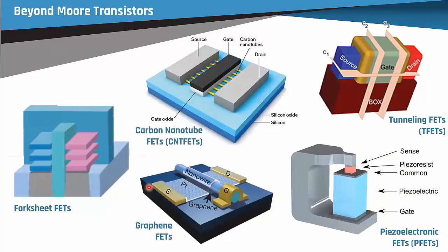However, there is a next step. Everybody's looking for what's next. And if you look at IMEC, which is a Belgian research institution that really comes up with a lot of the ideas that then go into our technologies at Intel and at Samsung and TSMC, they are already talking for the next generation about what they call a fork sheet, where the 2 different colors here are because you have a PMOS and NMOS transistor on 2 sides of the gate, which can really somehow make a CMOS within a much smaller type of area.